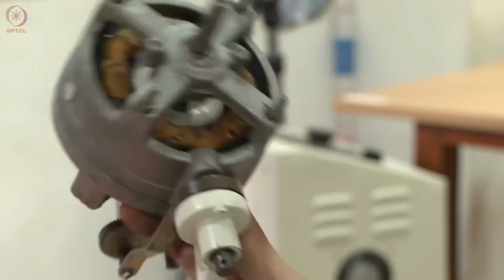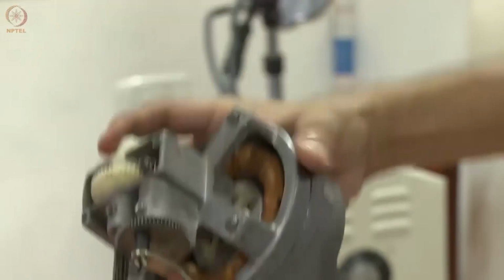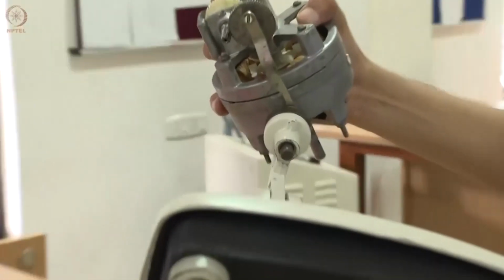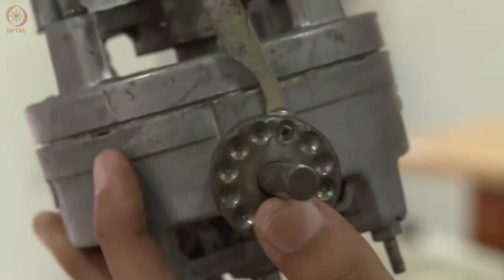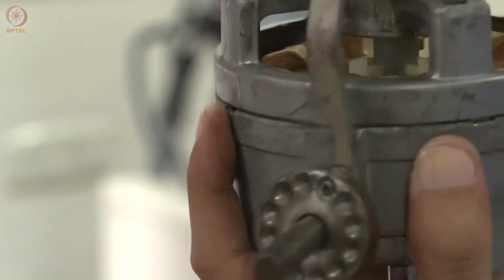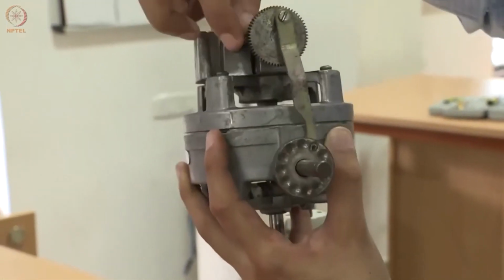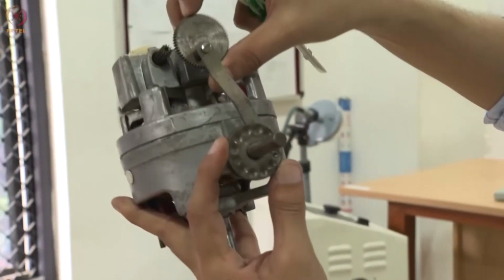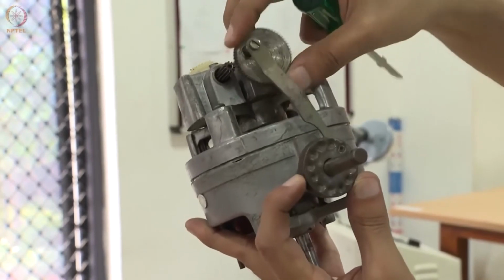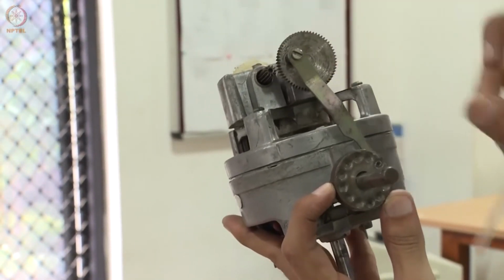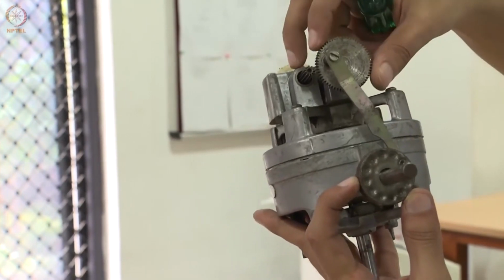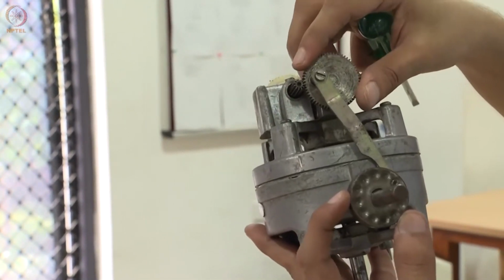Now the oscillatory mechanism itself uses what is called a 4-bar mechanism. So I hope you can see. Just to show you, let me just take out the motor. During operation, because it is engaged, I am unable to rotate it. Let me just. During oscillation, you can see, this behaves like a crank, and the entire fan body behaves like a rocker. So basically this is one of the 4-bar inversions.